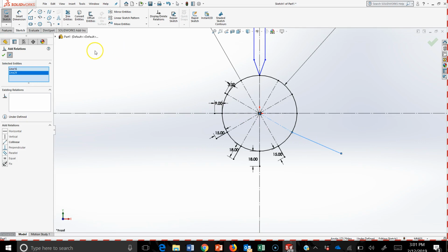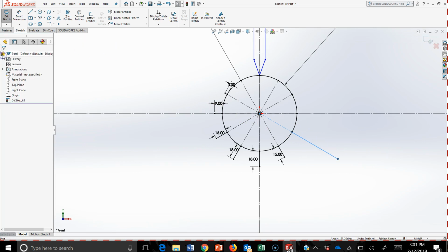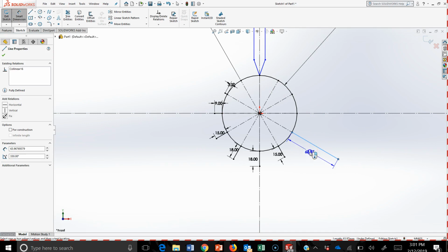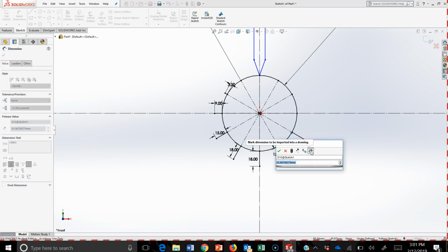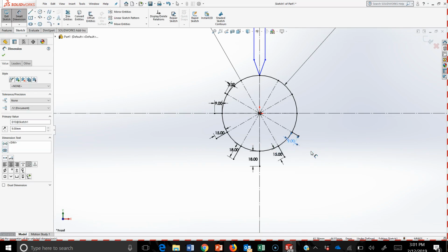The process for building a cam profile for the spherical follower isn't much different, except we have a few added constraints because we have to think about the center of the sphere as well as the edge of that spherical roller follower. All right, so we're at 210, 240. That's going to be 9 millimeters in displacement. You can probably see the symmetry here.